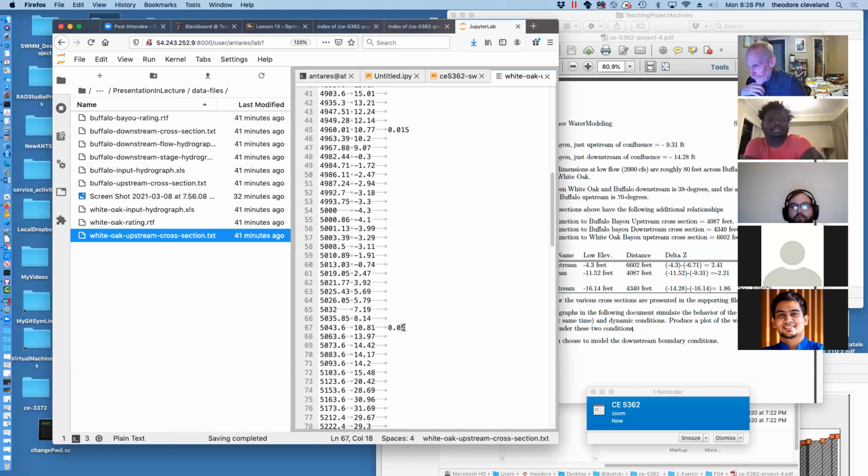That's something that would be appropriate if there's a lot of trees, or in this case, buildings or structure in the way that makes the cross section, at least in a one-dimensional flow construct, quite rough. 0.015 is the other extreme. That's actually a fairly small value of Manning's n associated with relatively smooth materials. In this case, that happens to be a concrete lined channel in that region.